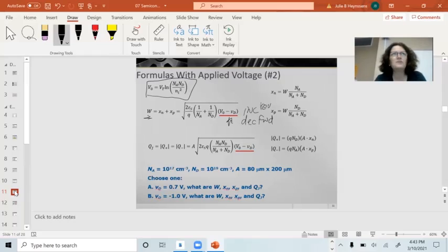That's my sanity check to see if I got the polarity right on my VD, to double check that. And you'll never have to take the square root of a negative number here, because if you make VD bigger than V0, you're going to burn your diode out. You're in the region where it doesn't matter.